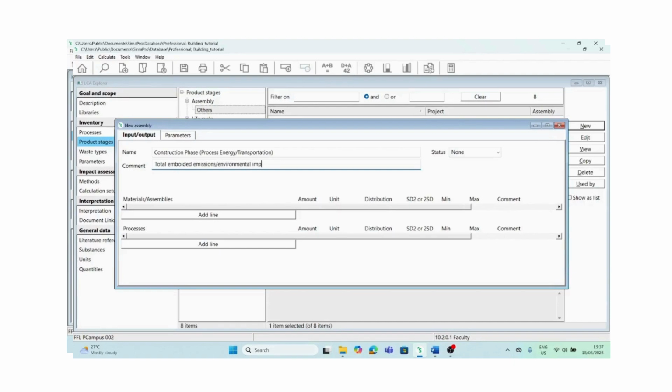we have to transport bricks, cements from market up to your site, and for these activities maybe truck or trolley, I don't know which type of means, but any category of means we have to use, and we should consider it properly here in life cycle analysis. That means total embodied emission, environmental impact during transportation, construction, such as mixing aggregates. Sometimes we have to use some mixer machine as well, and everything should be considered here.